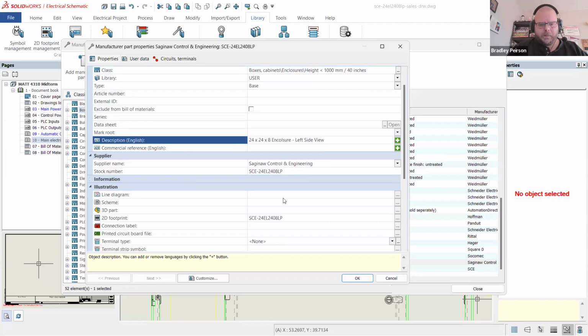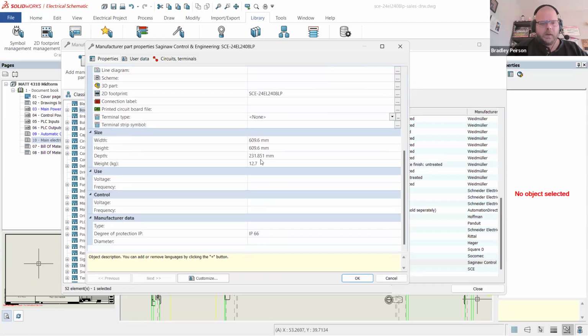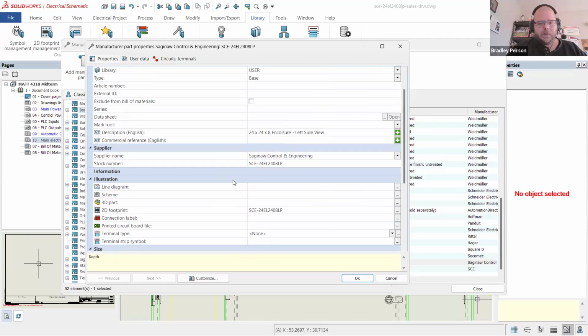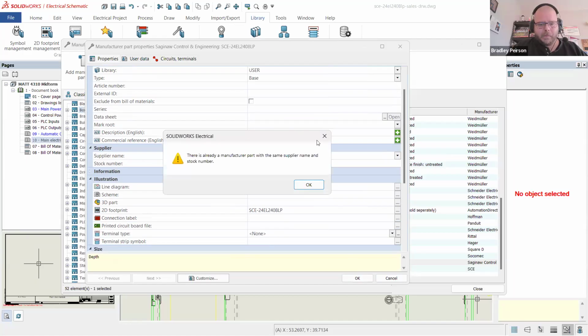Stock number, whatever. Yes, good. Dimensions. Now change. Important. Now change. So the width becomes the depth, and vice versa, because I'm going to be doing it from the side. 0.6. Weight doesn't change. I will change this in just a moment, but for now I'm going to accept that.